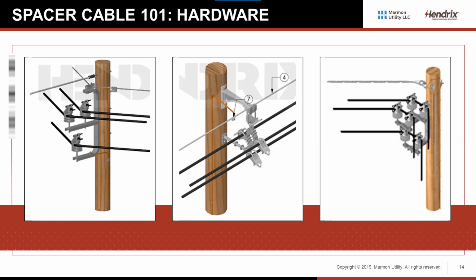So obviously you're dealing with a lot more weight. So it has to be a lower class pole, a beefier pole, but that still tends to be a little more cost effective than going with a pole that's 5 or 10 feet taller.